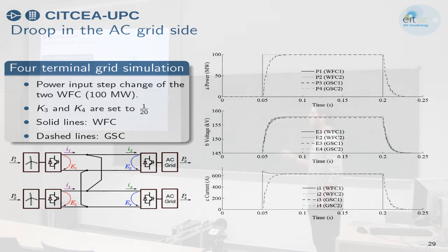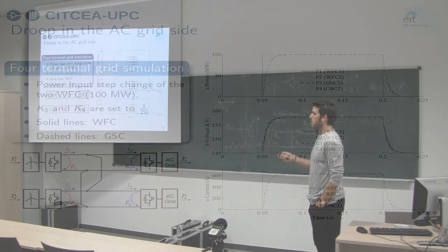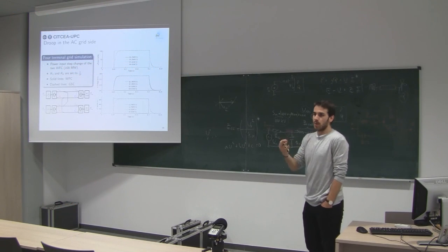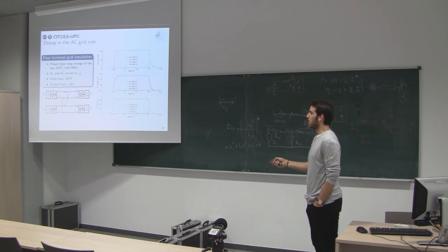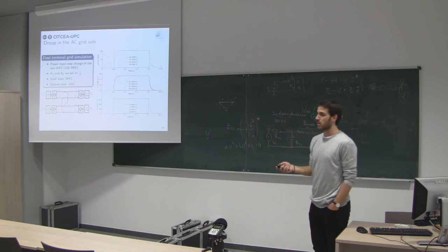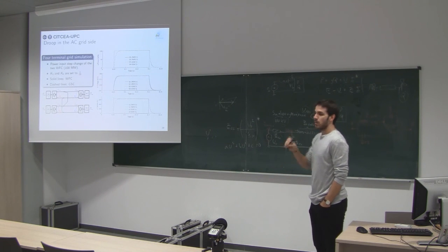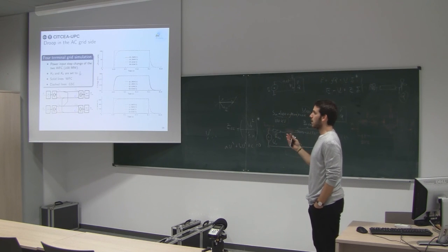For example, regarding voltages, here you can see the reference voltage, and as soon as you have this power input, as you have the proportional controller, it stays under, I think we defined for this case, a maximum deviation of 10%. So here you can see that it is evolving to the steady state, but it's less than 10%, right?